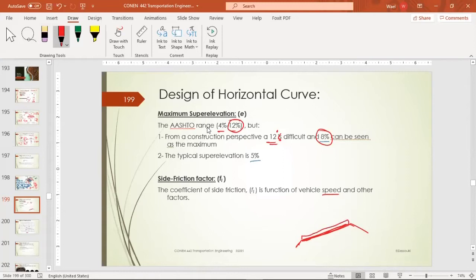When we try to compact it, there is no firm thing for the equipment to drive over. Okay, so usually we build a support here. Then we have the finisher. That's the machine that we use to place the asphalt over this part, but supported here, so it doesn't slide this way.